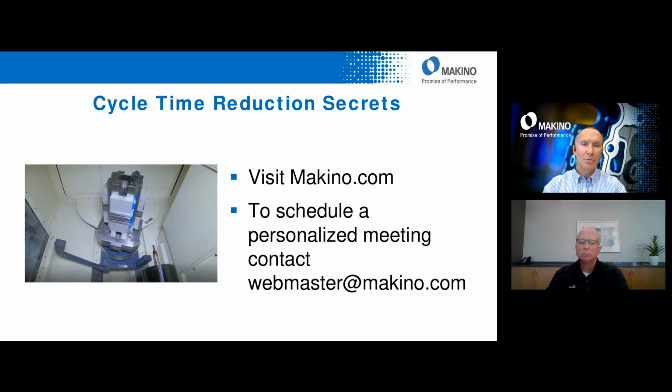Okay, thank you, Mike. And we have another question from Edwin, who's asking, does M9 apply to just the coolant command, or would it also work for air? So M9, that's a good question. I believe it does work for air. M77 turns your through spindle air on, and yeah, I believe M9 does turn that off.